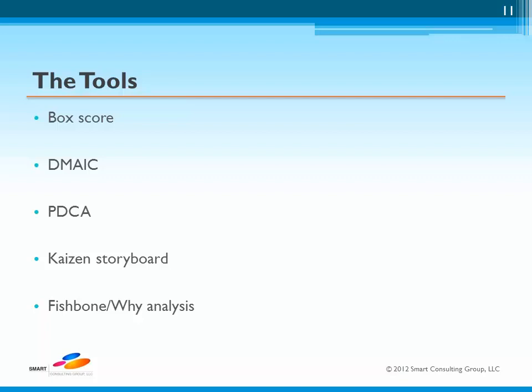The box score. The box score is a summary chart which records key performance measures for the process being studied. Typically, box scores will display total lead time and value-added and non-value-added times for that step. Other stats may include cycle time, takt time, changeover time, the number of pieces or the number of units per shift, scrap, and uptime. Depending on the focus of the exercise, it may be most beneficial to limit this information to prevent information overload, which would be confusing. An important point to stress here is that the lead times and the takt times set both the tone and the way for the overall process to be performed.